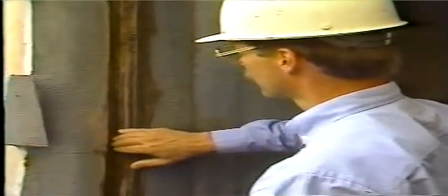One type of corrosion, called galvanic corrosion, occurs when two dissimilar metals that are touching each other come into contact with an electrolyte, such as water. As with other features subject to high-velocity water flows, gates and valves can suffer from cavitation. Also check the housing or frame for damage, bent members, and misalignment, and examine seals for signs of deterioration.